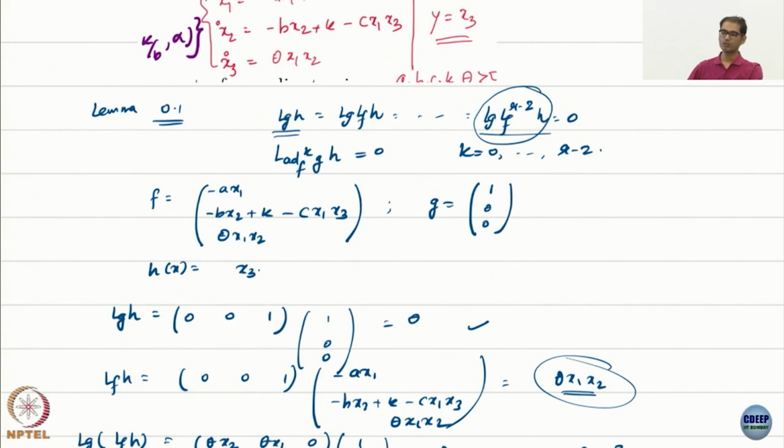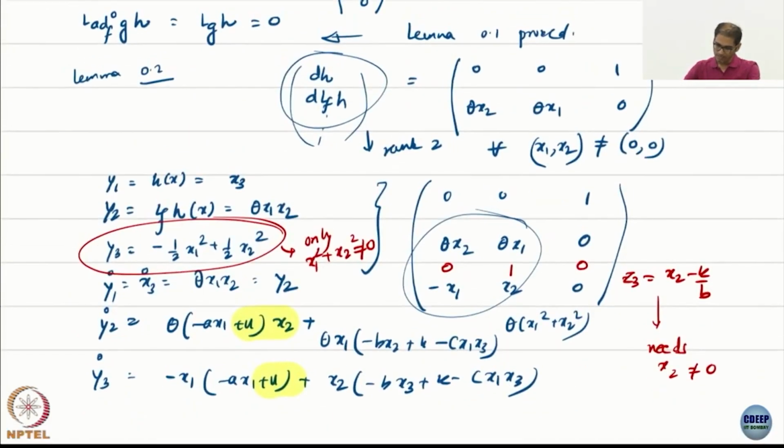Fundamentally there are robustness issues with feedback linearization, it's not Lyapunov based, as you can see you are cancelling things, we will keep trying to cancel things. Even this dynamics we saw in the end, if you see, you got this structure, right, a rather complicated looking structure here, you got the control here and you got the control here.